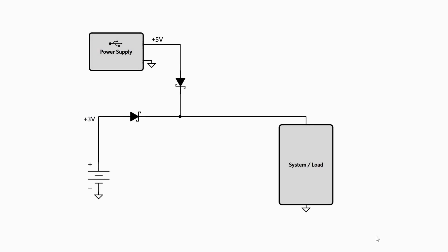I'll talk about a few industry standard ways to do diode ORing, and then show you the tiniest possible diode ORing circuit using the MAX40200 ideal diode. The classic approach to switching between power sources is to use Schottky diodes, as they are simple two-terminal devices and have a low forward voltage to reduce power loss. When the outputs of two Schottky diodes are tied together, the one with the higher voltage applied conducts, which reverse biases the other diode. However, using Schottky diodes poses two problems.